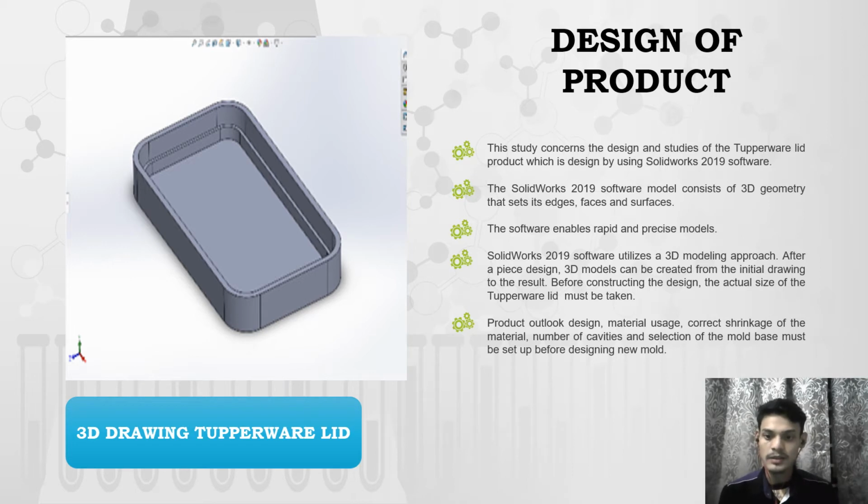Before constructing the design, the actual size of the Tupperware lid must be taken. Next, product outlook design, material used, correct shrinkage of the material, number of cavities, and selection of the mold base must be set up before designing a new mold.